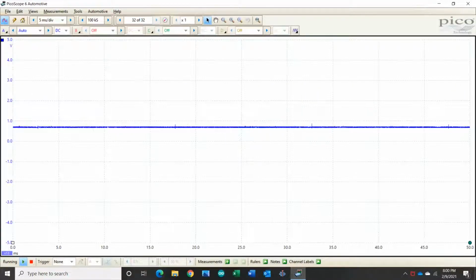So in this demo mode, it looks like they're trying to show us an injector waveform, and as we can see, it's jumping around erratically. That's what an injector waveform looks like. For some reason, the voltage level is low on this waveform. Normally this would operate at 12 volts, but anyhow,